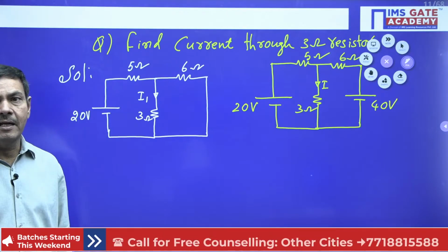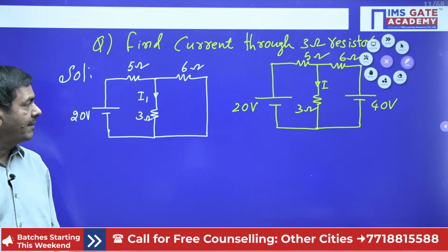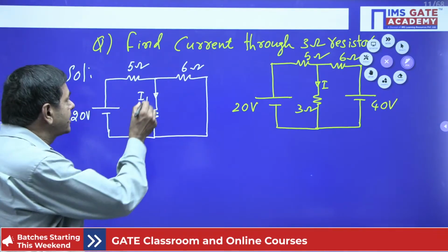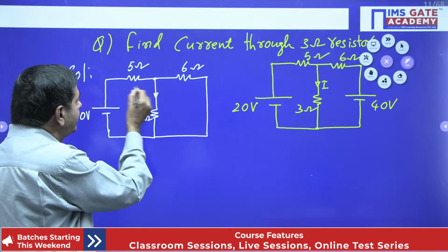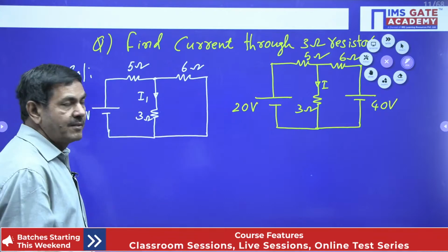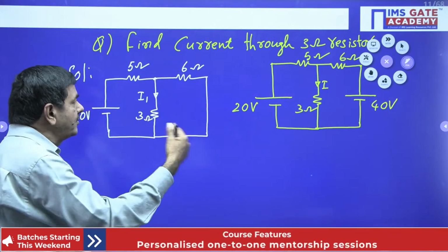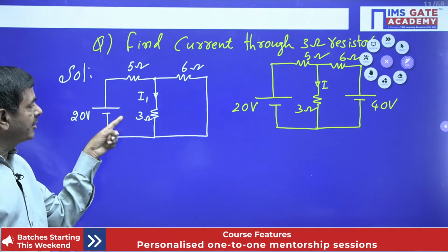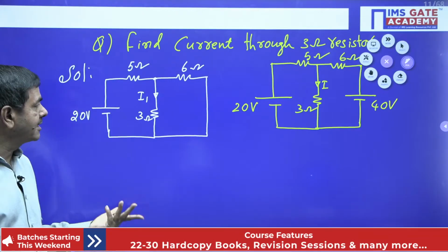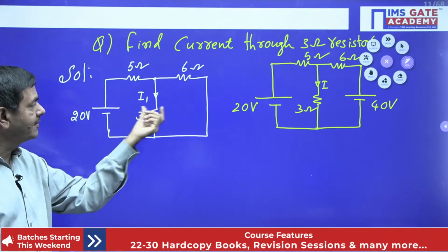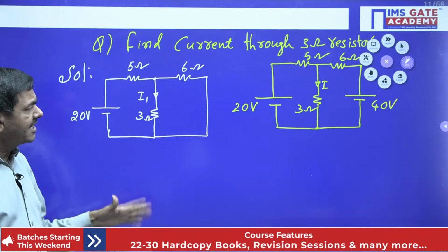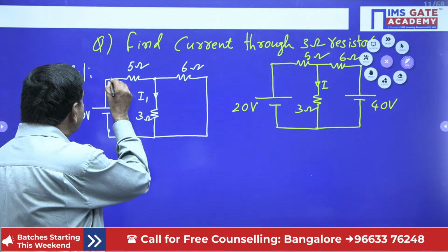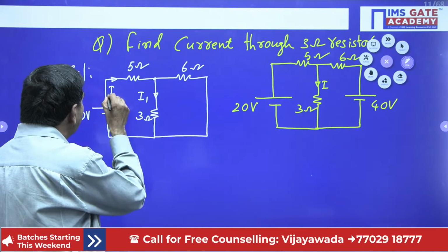But this current I1 can be calculated in different ways also. By using nodal analysis we can do it. By using nodal analysis, this node voltage we can take as V. This current plus this current plus this current you measure. Current I1 equals voltage by 3 ohm. That is one method. The second method, we can take Maxwell's loop method. According to Maxwell's, the difference of this current and this current will give I1 itself. You find out the net current passing this side. This current we can assume as Ix or something, for example.